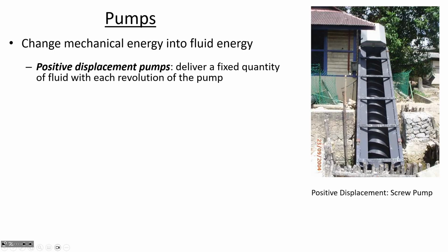All right. Pumps add energy. And water flows through a network because there's more energy upstream than there is downstream. And sometimes there isn't enough energy to overcome pipe friction. Sometimes there's not enough existing energy upstream to overcome an elevation difference. So if we want to get water from one point to another, often gravity flow isn't going to be enough. And so we have to add additional energy to get water moving as quickly as we want or to overcome resistance, whether it's an elevation change or frictional resistance or whatever.